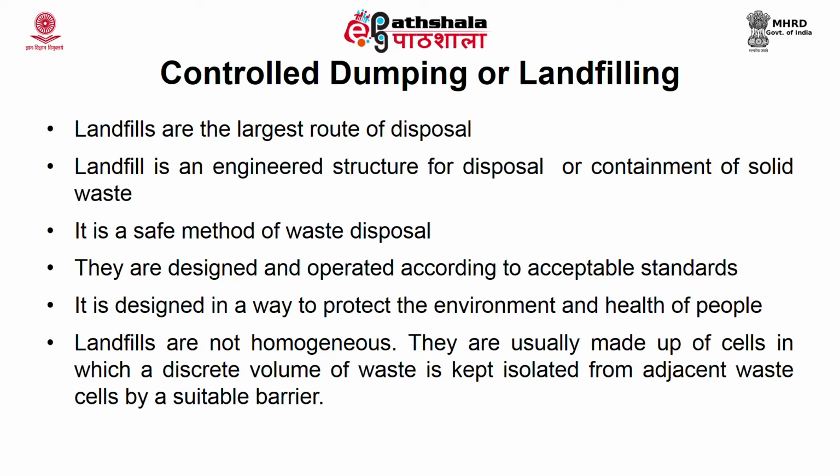Landfills are not homogeneous and are usually divided into a number of cells with a discrete volume. These cells are imaginary and each stores a specific volume of waste and is kept isolated, that is, each cell is separated from the other by means of a suitable barrier. So, landfills are usually made up of cells in which a discrete volume of waste is kept isolated from adjacent waste cells by a suitable barrier.